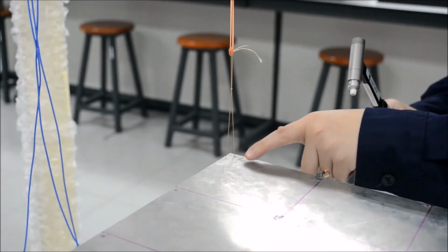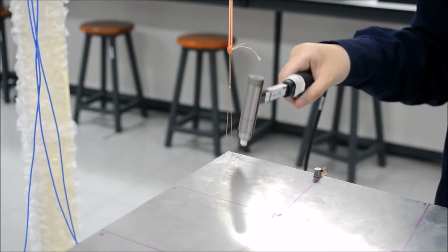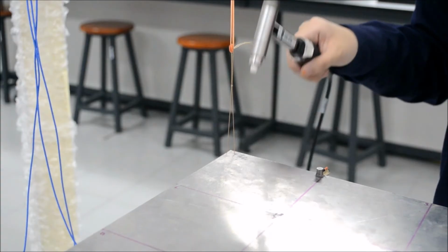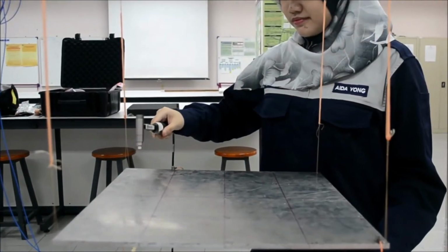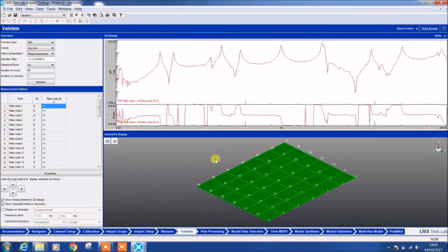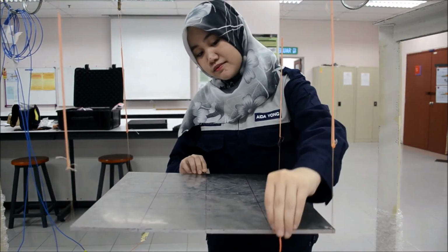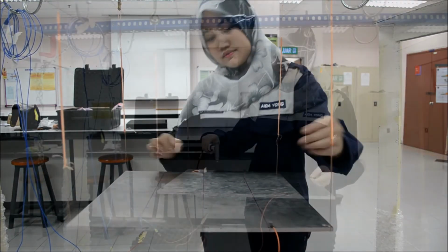Introduce impact on the thin plate structure at the reference position, by using the impact hammer with a plastic tip. Repeat the impact 10 times for every measurement, to get the average reading of the response measured. Averaging a number of signals should increase the reliability of the measurement. Rove the 2 accelerometers for every measurement according to the sequence list, until all the nodes are measured.